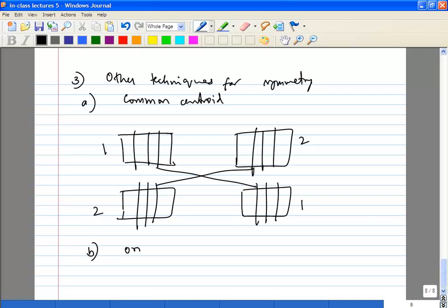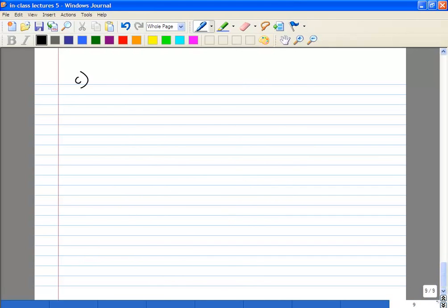Obviously other very basic things: orientation. If you want to match 2 transistors, let's say one was like this, you're not going to make the other like this, that's for sure. That's very stupid, right? So you're definitely going to make sure they have the same orientation, right? Dummies.